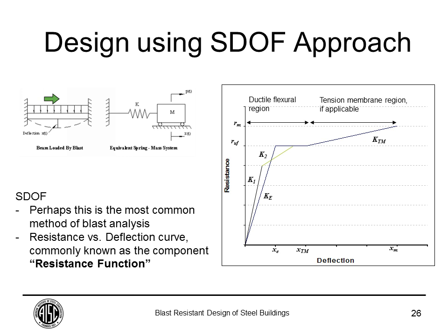So what we do is we pick the dominant mode of response, or the mode of response that we want to design that element to behave in, and create a single degree of freedom that represents that one mode of response. If you develop a single degree of freedom to trace the flexural response of a member, you do not want to use that to assess the shear capacity or the dynamic shear response of the member. So you need to be careful that once you develop a single degree of freedom, you know what it represents in terms of the real behavior of the component.